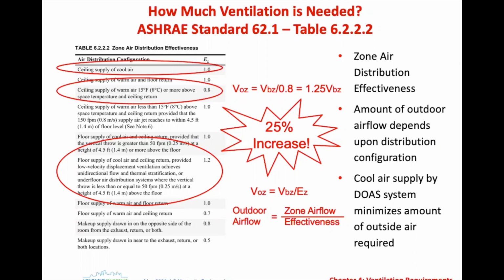The whole room would be smoked up almost universally within a matter of minutes. If that air was warmer or cooler than the air in the room, it would create a cloud and not mix as readily. Or if it was cooler, it would be on the floor and it would not mix as readily. It didn't diffuse very readily into the room, and we weren't diluting pollutants in the room as well as a result of that. So that's a really important factor to consider.